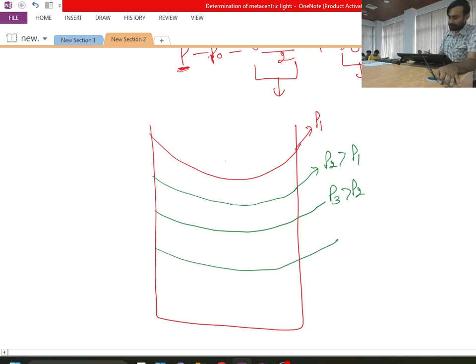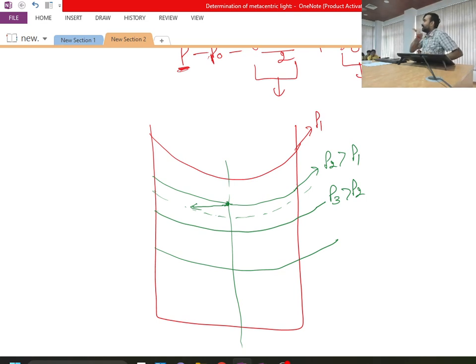Okay, so from this point, one important observation is, if you are at the same elevation, if you don't change the elevation, then the rho g z component is not changing. If you are at the same elevation and you move towards the outer side, then you are entering the higher pressure side. Generally we say that if I am on the same elevation, then pressure is not changing.